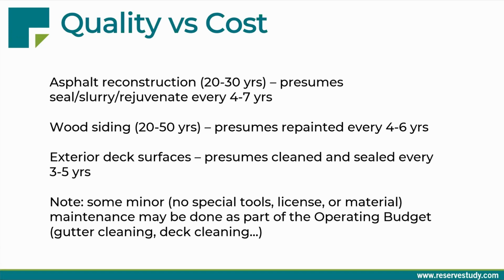The wood siding useful life is based on the presumption that it'll be repainted every 4 to 6 years. Exterior decking, we are assuming that, and these will all be additional line items on your reserve study, that the sealing will be completed. And also, in some situations, the operating budget will reinforce the reserve planning with the annual maintenance that you aren't handling from reserves. For example, gutter cleaning or roofing or decking cleaning, like clearing out those drain lines, or hydrojetting the drain lines. These maintenance projects that are being handled from the operating budget are also benefiting the reserve budget by extending some of the useful lives found on that report.